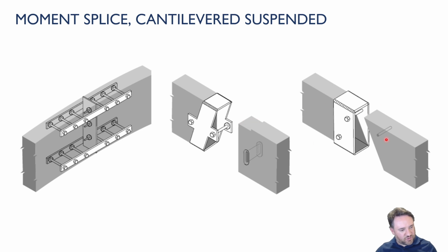Okay, and this is a similar detail, just using a collar type of detail instead of this one. So here I have flat ends on the beam. This one I have to taper, I have to angle the end of the beams in order to accommodate that connection. You're probably not going to run into this too much because it's not very common to try to do moment connections in timber. And I mean, you might have multi-spans where you have a cantilever and then another one sitting. That could be possible.